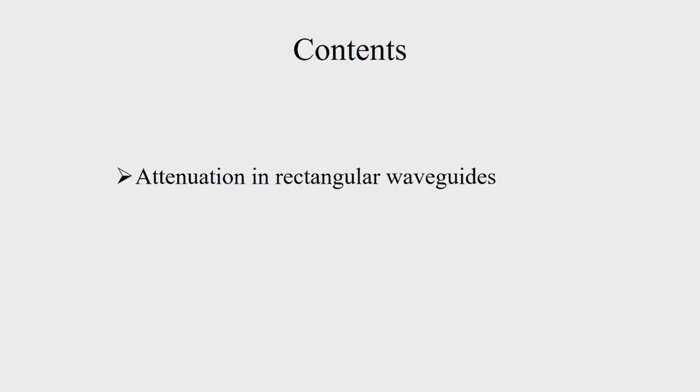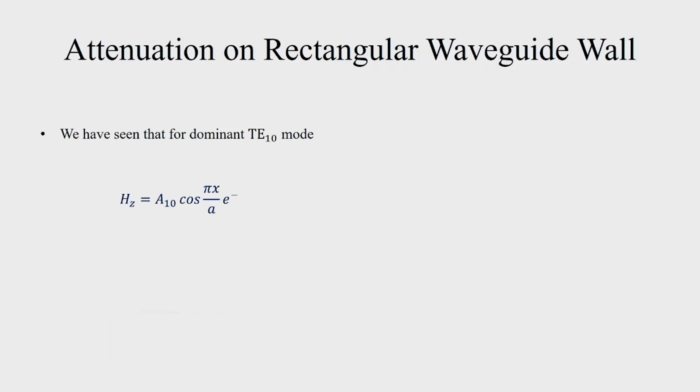We now cover these two topics, attenuation in rectangular waveguides and attenuation in circular waveguides. We start with formulating the attenuation in rectangular waveguides. We will restrict our discussion to the dominant TE10 mode only, and for the TE10 mode we have seen the longitudinal